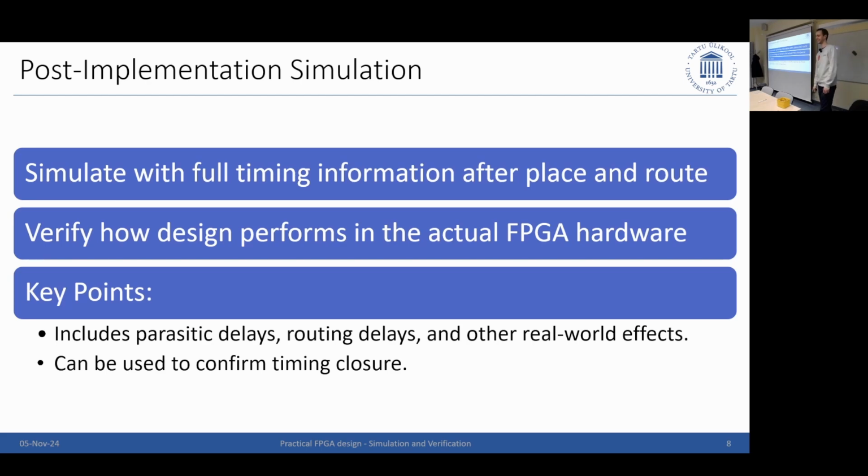You said it can take a whole day or longer. Why is it so? Isn't it just running it like a real application, but just checking metadata? You need to consider that already in behavioral simulation, it can get quite slow, because if you have a big design, you have hundreds of thousands of signals which need to be simulated for every time step. And when you then put in not only the signal on and off, but also propagation delays through the design, this complexity scales with the amount of signals, and that's when you get a lot slower. So basically brute force is everything that can happen. Yes, pretty much, if you want so.